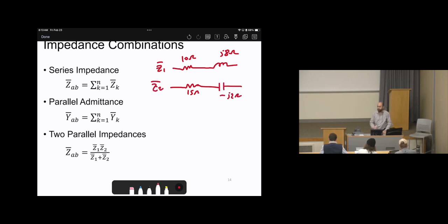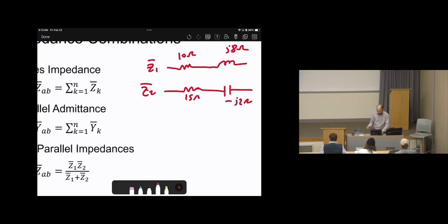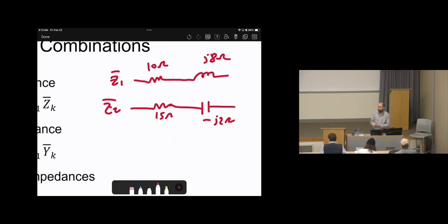So by looking at this, everything is in phasor domain, so everything in ohms, the capacitor in ohms, inductor in ohms, then that's fine. I don't need to convert them to phasor domain. The next step, I need to calculate Z1. So look at Z1 bar, 10 ohms, and the inductor. Are those sharing the same current? Yes. Then I can make them a series.